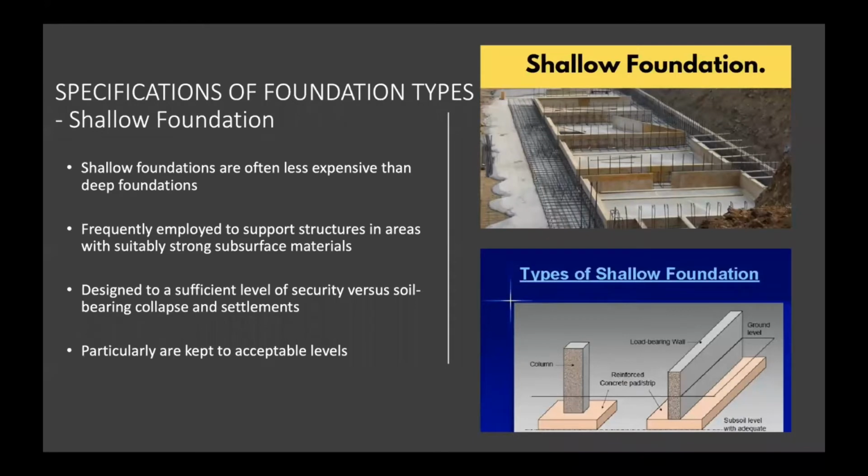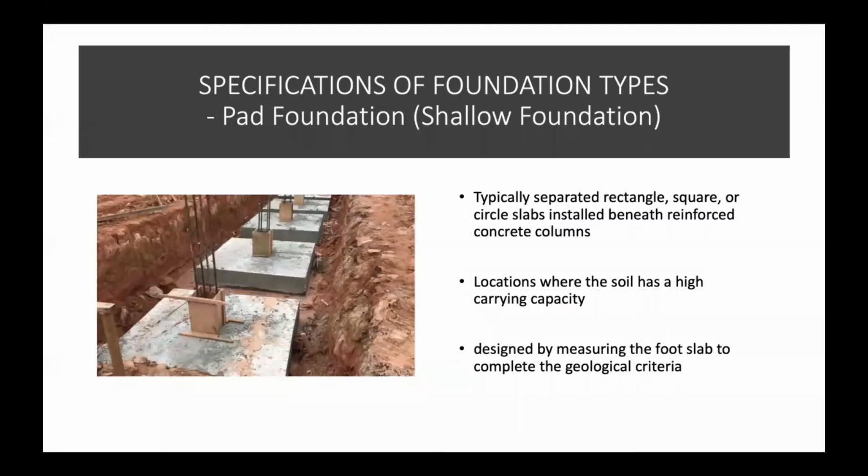Shallow foundations are often less expensive than deep foundations. They are frequently employed to support structures in areas with suitably strong surface materials. The pad foundation is one of the shallow foundations. It is typically a separate rectangular, square, or circular slab installed beneath reinforced concrete columns.